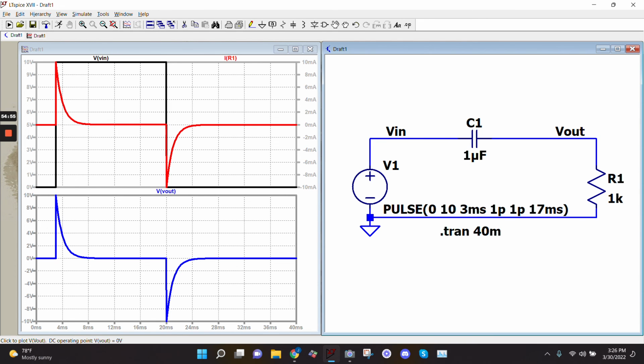This changed by 10, this changes by 10. If this were to drop down to some crazy negative 150 volts, this would have to go down to negative 140 volts to keep that 10 volts across it, or negative 160 volts. It has to just maintain the voltage difference across the capacitor. Correct. Were you going to ask something?